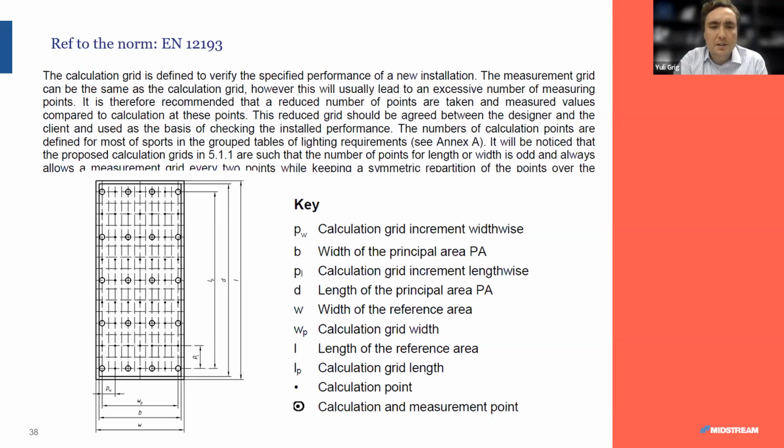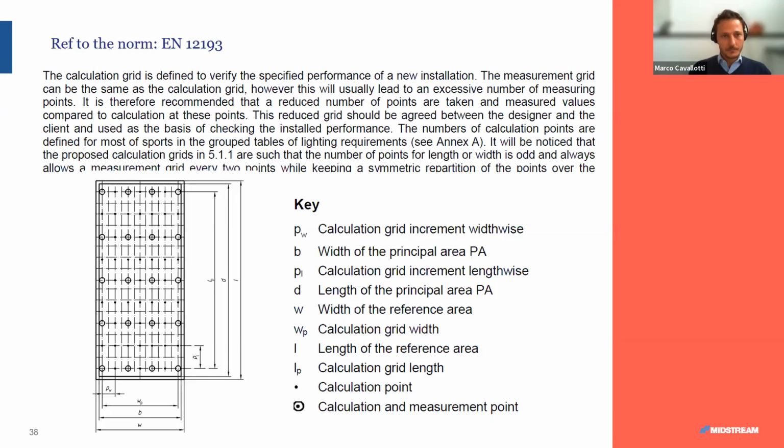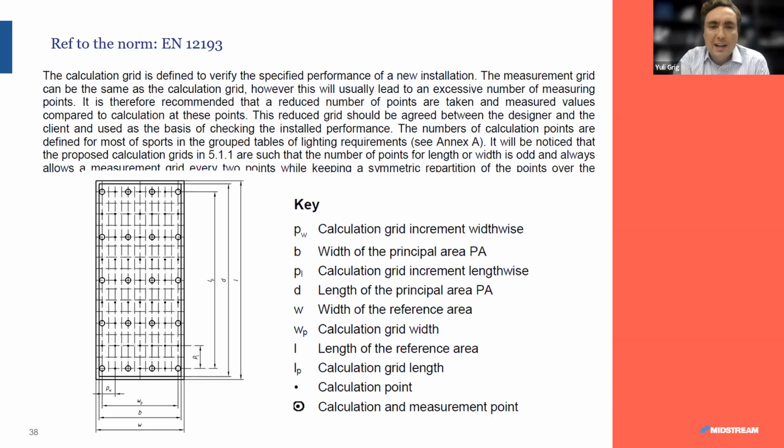That's fine. I'm just going to tackle a couple of quick questions. We've got one here from Imad, who says, hello, in which standard can I see that the standard is 50 lux, not 20 lux for cargo apron? That's covered by EN 12464 outside space. Under table 5.2 airports, there's something called loading areas, and for reading labels, they recommend 50 lux average. So that will be in that particular standard.